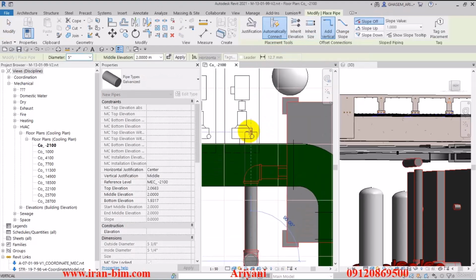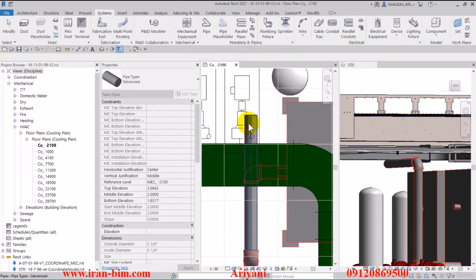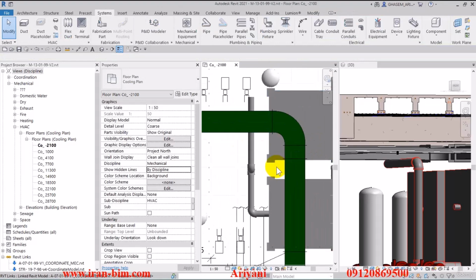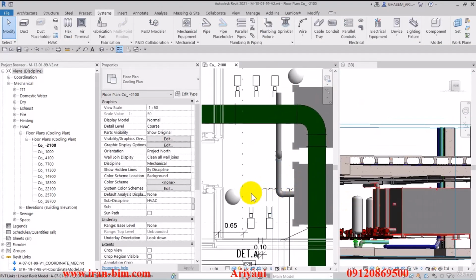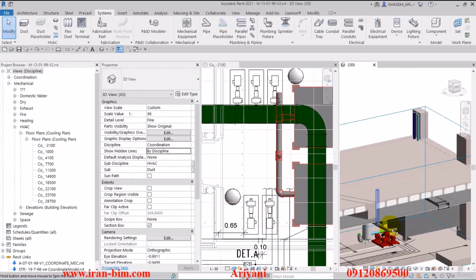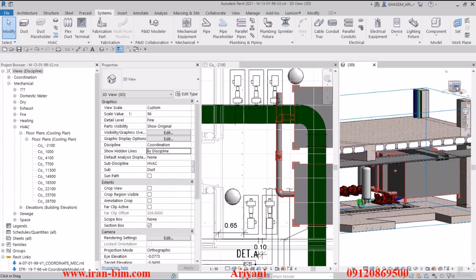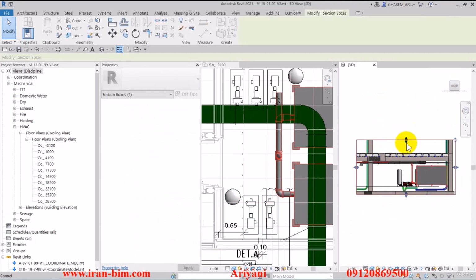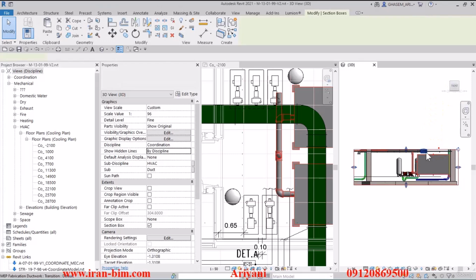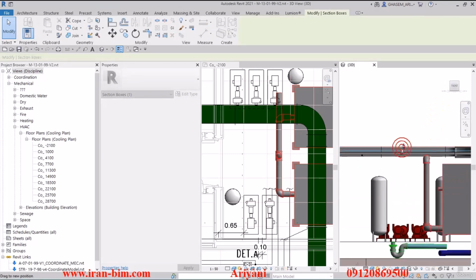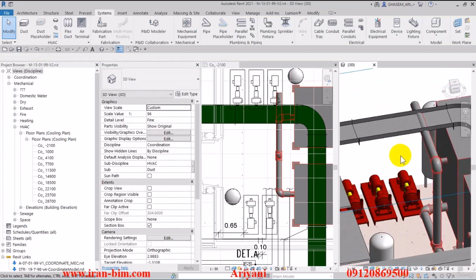Now right click on it in the 2D plan and select draw pipe. And we'll bring it up to here. We can leave it here for now, but then later on we'll have to bring it inside of the booster pumps. And then they have another pipe that goes down here. Now let me go to the 3D plan and bring the cut up to this point and rotate this to, let's see, the front view, and then rotate it once again to this point.